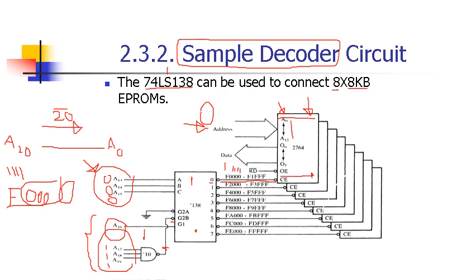For your ending address, you provide 13 ones. For converting them to hexadecimal digits, you take a 1 to make the hexadecimal digit here, which would be 1. So F, then 1, and the other 12 would be 1s. So this would be your ending address of the first memory chip, or the 0 memory chip.